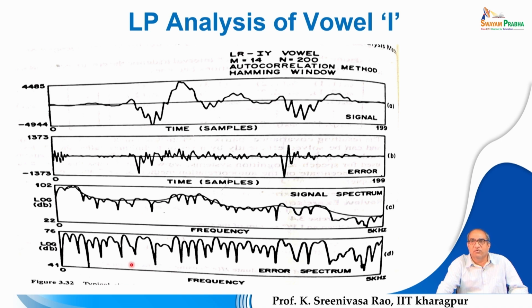So, you can observe over here that this is a flat spectrum, right. Here the error signal has a flat spectrum with simple ripples, whereas your vocal tract filter response is very smooth. So, if you want to generate the speech spectrum, you multiply the LP spectrum with this flat error signal spectrum, and you can see the corresponding speech spectrum, right. This is very evident, because the rippled plot in plot 3 is nothing but the spectrum of the vowel segment.